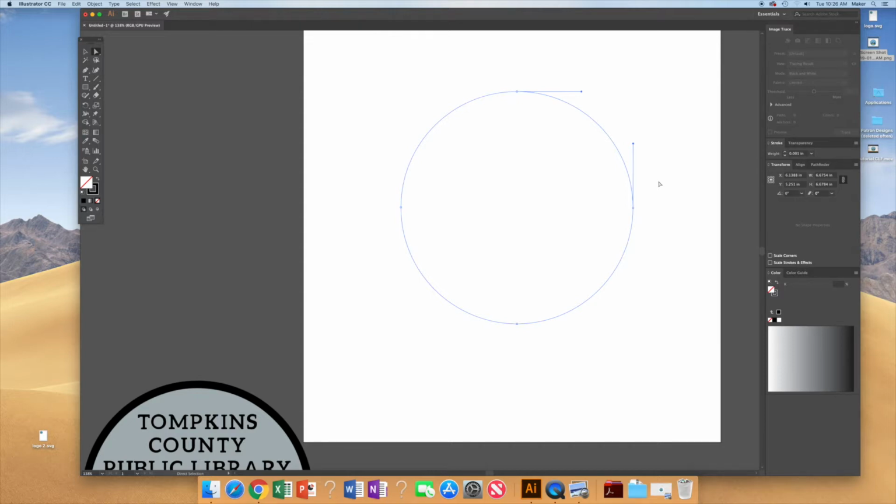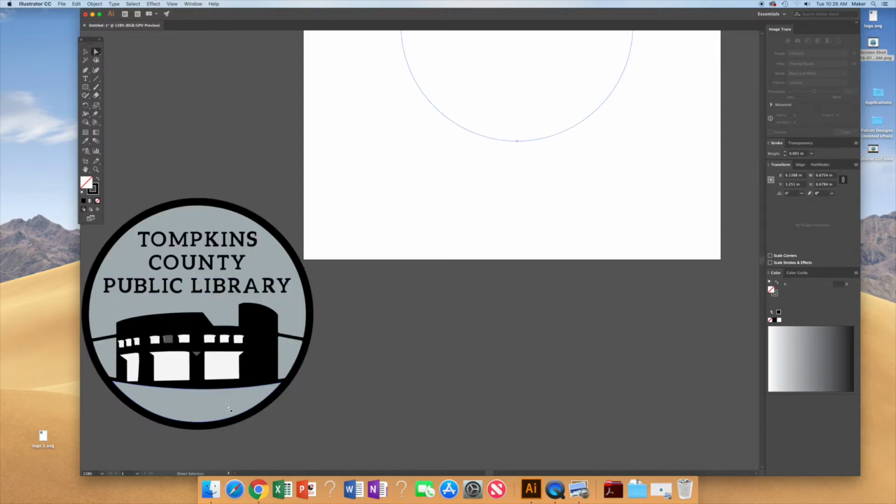So if you had a whole design that had the weight of 0.001 on all of its outlines, it's going to cut out every shape in that design. In this design, I want it to engrave the part that has my company name on it. I don't want it to cut out all these different separate letters, so that's why I'm not giving these that same stroke weight.